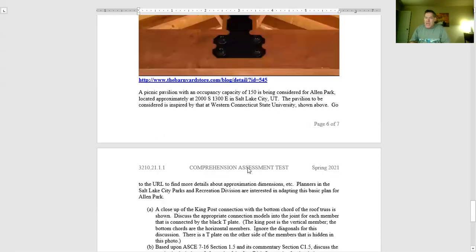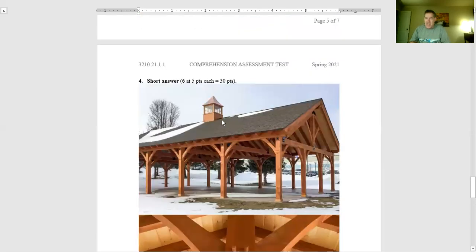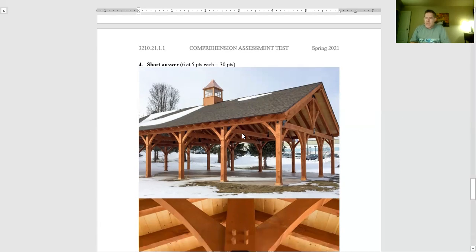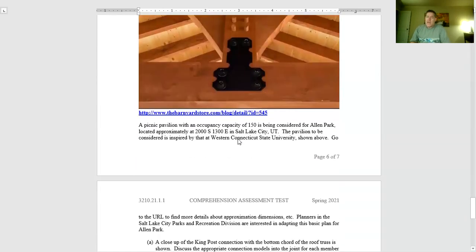We're not assembling on this structure, are we? So even if we call it a flat roof, for the purpose of this exam, we're still not assembling on it. So therefore, that's 20 PSF. Now, if you go through for sloped roofs, you can actually get a reduced value, but 20 PSF would be the starting point for our situation.